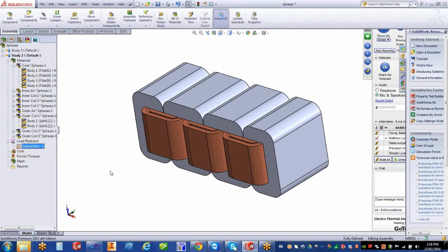It's really the only thing you need to do: to say, okay, I want to couple the thermal, and this is a liquid applying a convection on the device, nothing else. The simulator will automatically take all the thermal losses, namely the ohmic and core losses and eddy losses, and apply them automatically.